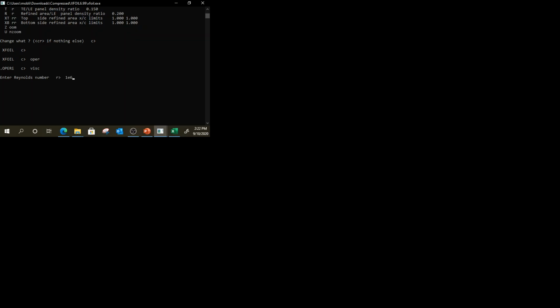All of these things are design parameters. Let's say you decide to analyze NACA 2412 at a specific altitude, right? At a specific Reynolds number, at a specific cruise speed or whatever, right? You have to calculate the Reynolds number and the Mach number, all of them, and you have to plug those in, right? So the predefined Mach number is 0. You don't need to change it, but if you want to have a more accurate analysis, of course you have to change it. And then number of iterations.